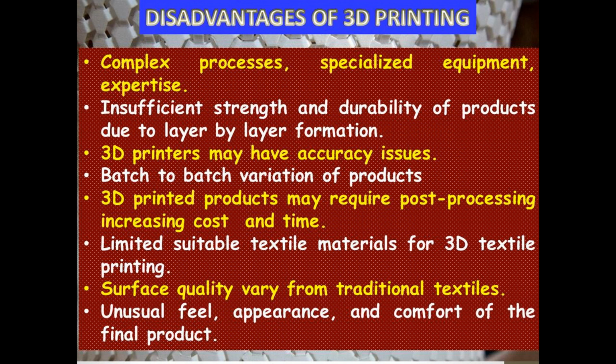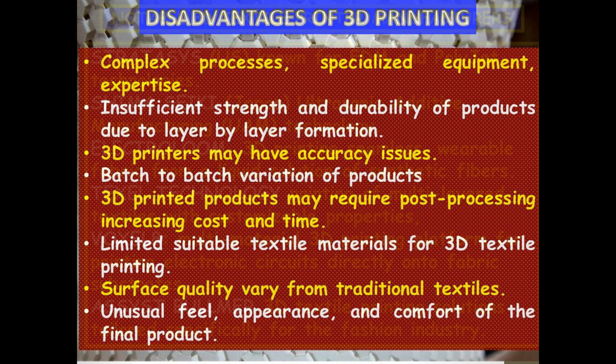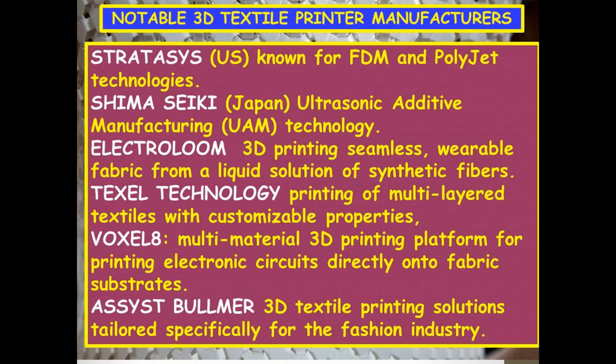Disadvantages of 3D printing: complex processes, specialized equipment, expertise required, insufficient strength and durability of products due to layer by layer formation. 3D printers may have accuracy issues. Batch to batch variation of the products may be possible. 3D printed products may require post-processing, increasing cost and time. Limited suitable textile material for 3D textile printing. Surface quality varies from traditional textiles. Unusual feel, appearance and comfort of the final product.